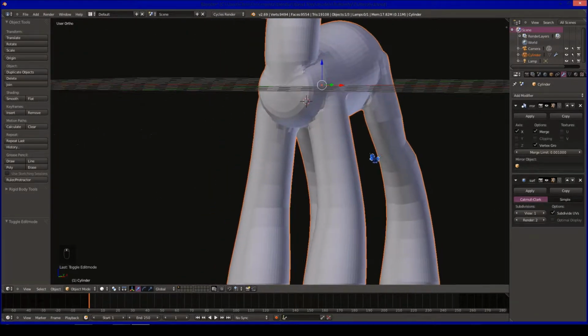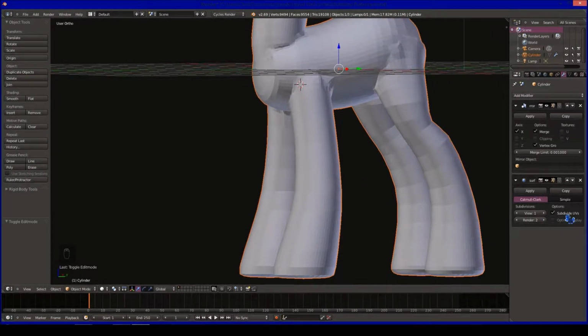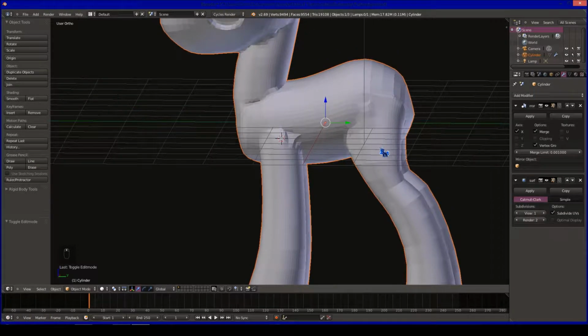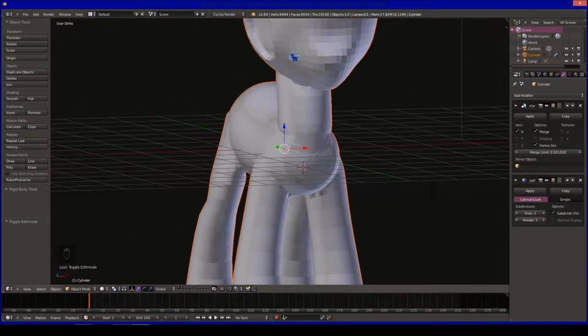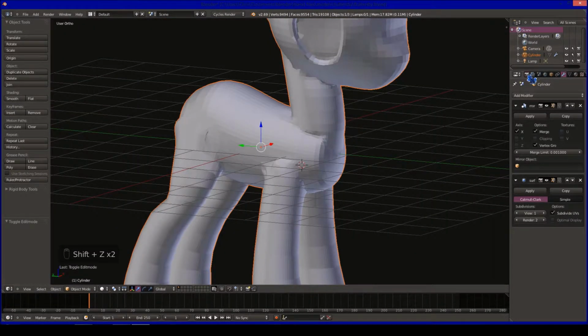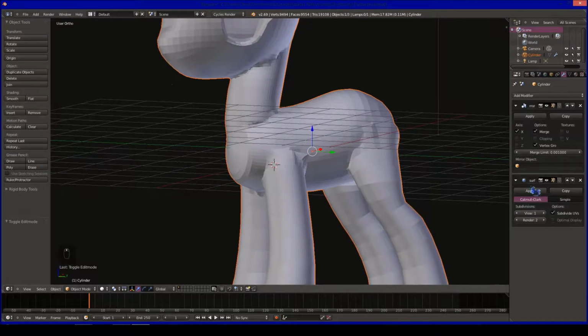One thing that you are going to want to do is I would very strongly recommend you do not apply this at all, especially if you have a lower power computer, because this will very much start chewing your computer to pieces. You've got two options. You've got view and render. Render is automatically set to 2, view is automatically set to 1. This is just how many times this modifier is going to subdivide the model in the view, in your 3D view like this, versus your rendered view, which is not that. It's when you actually click the render icon, and it'll actually finalize render the image out.